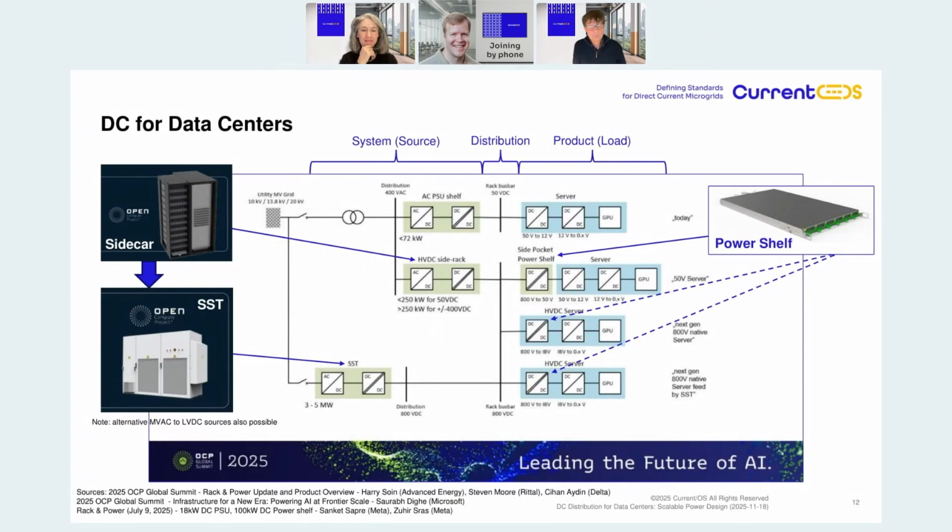On this next slide here, what you can see is these 2 stages of DC usage within the power incoming to the IT rack. First, starting with a sidecar where the voltage incoming to the sidecar is still AC, but is converted over to DC and then utilized either at plus minus 400 or 800 volts for the IT rack.